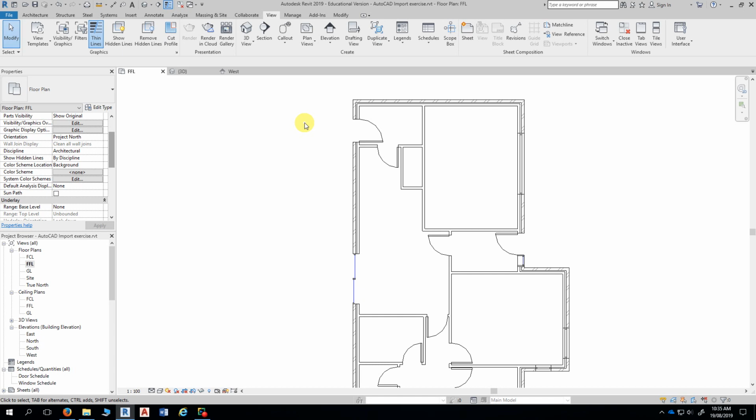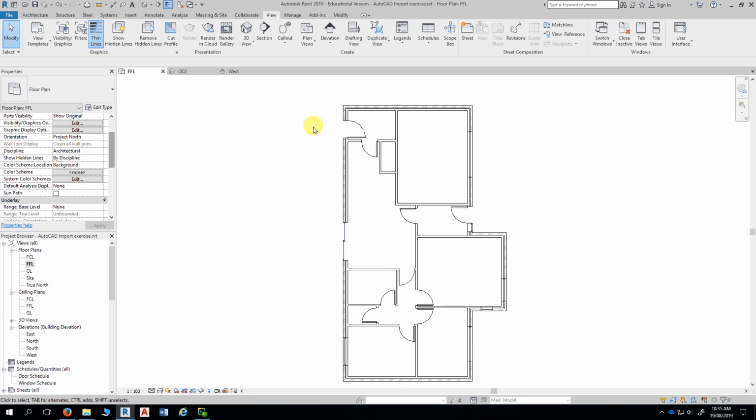Now, the question is, at what height is the software cutting through the building? You set it to the ceiling height. No, well, again, these are all rhetorical questions because I guess the thing is that it's not cutting through the first floor, is it? There is a predetermined height at which the software cuts through the building to allow us to see the building like this, as in a floor plan. So the walls are being cut through, the windows are being cut through, everything's being cut through at a set height. Now that height happens to be 1.2 metres. Okay.